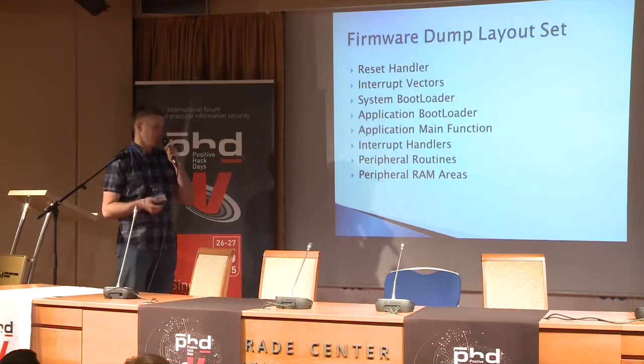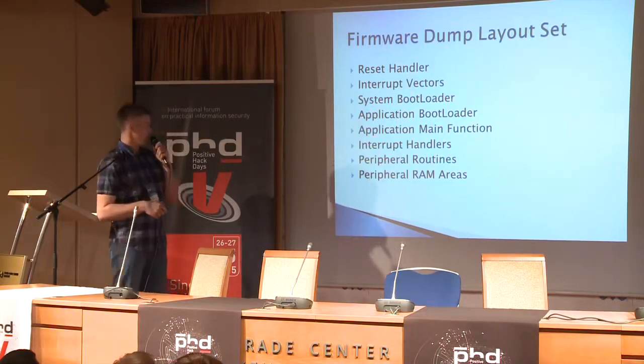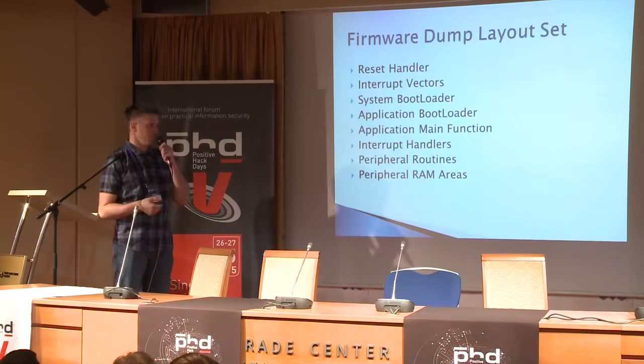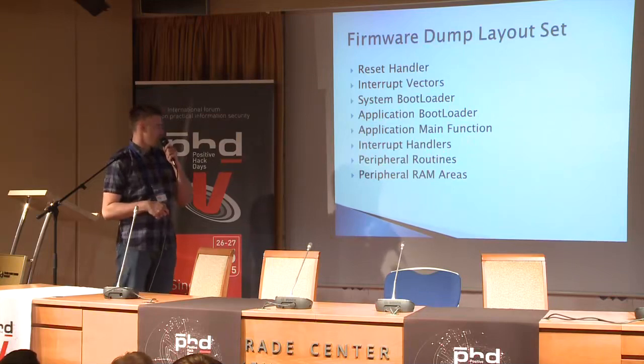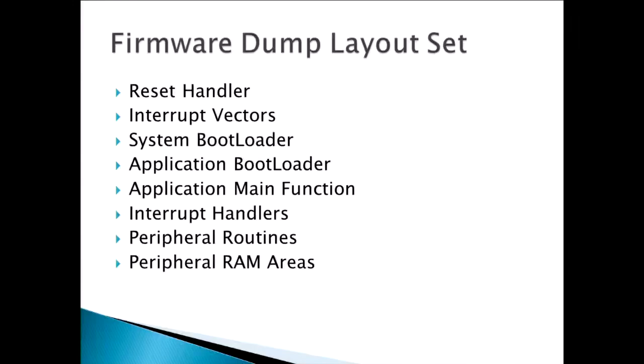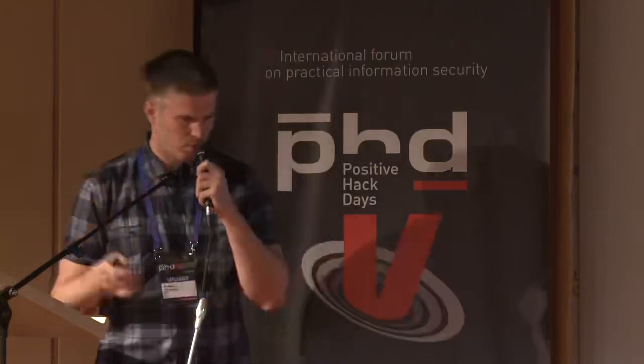Then we have a system bootloader, which prepares all of this. Then application bootloader, which boots the main application. Then main functionality application. There could be interrupt handlers, but some of them don't need it. And then some peripheral routines like CAN, BUS. I'm not going to give you any lists of this.